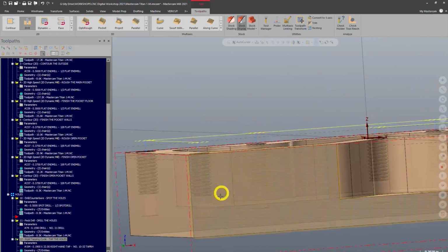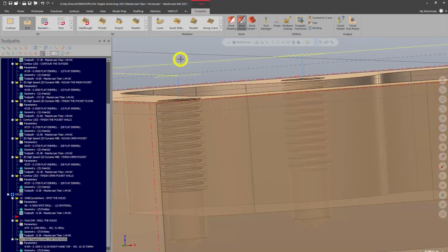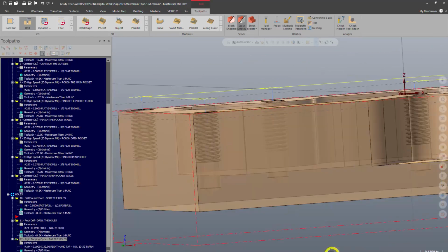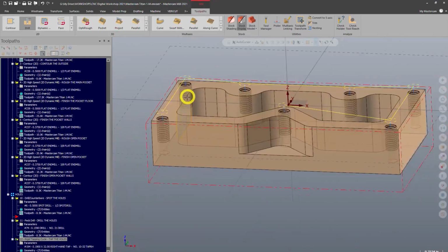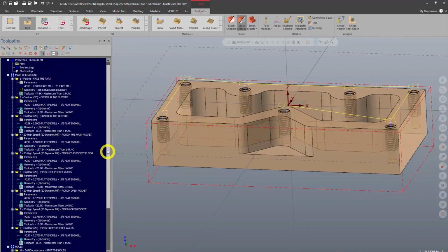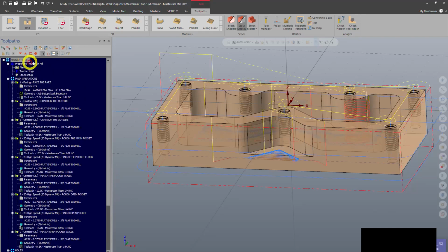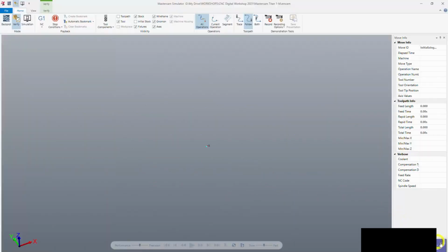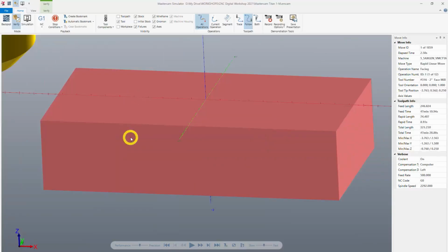So now we can see the depth of our tap is right beyond the threads that have been called out and cut into the model, but not so far that it's going to bottom out on this hole. Perfect. So let's run our whole machine group through verify and see what we've got.